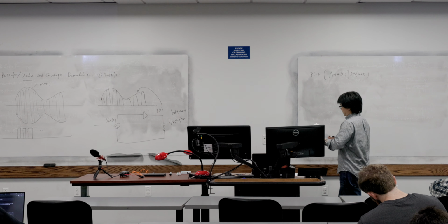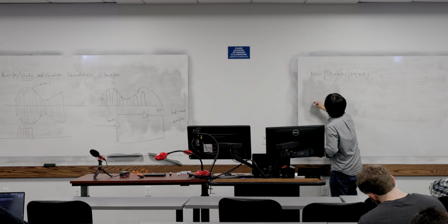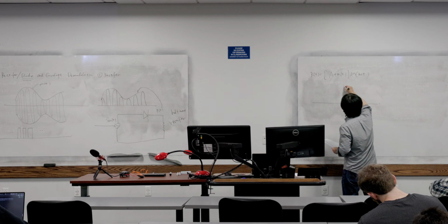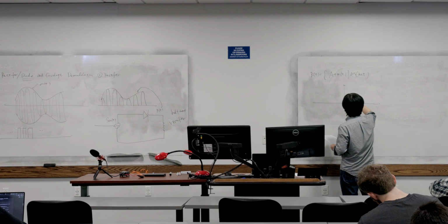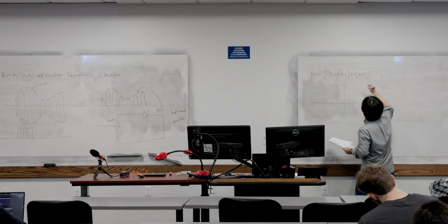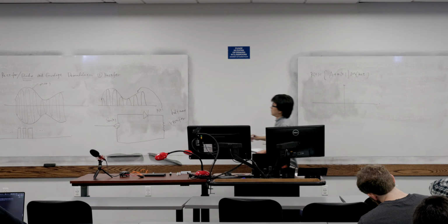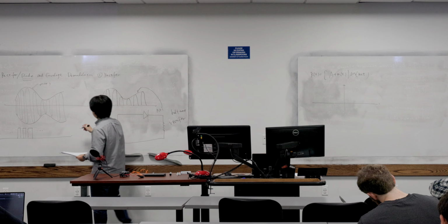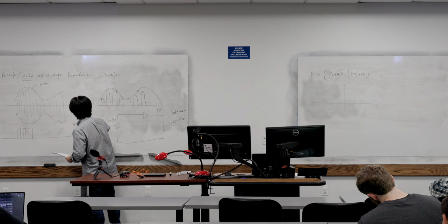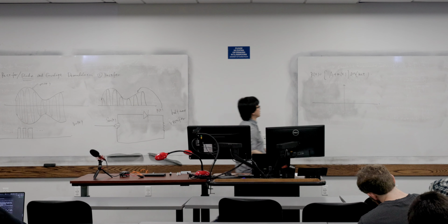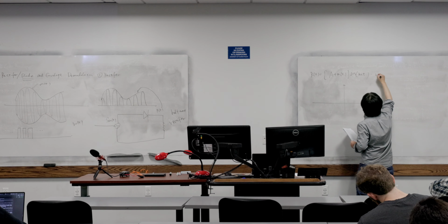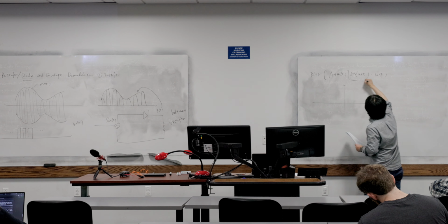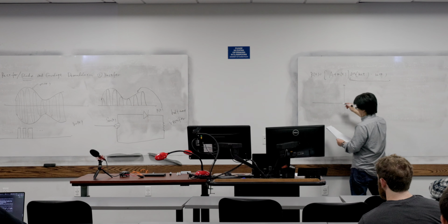Let's say we denote this square wave as w(t). We multiply our signal by w(t). So the cosine multiplied by this is nothing but something like this.